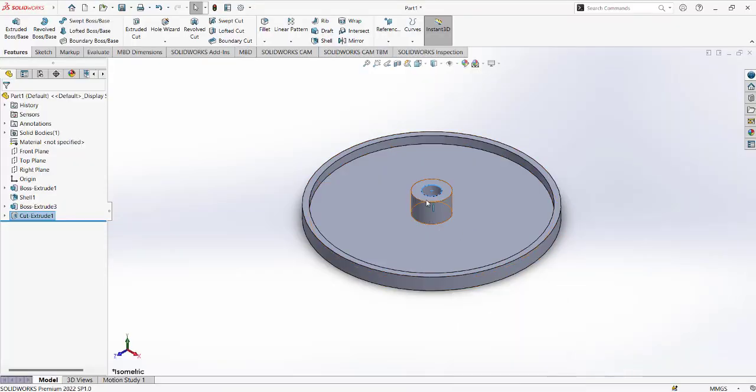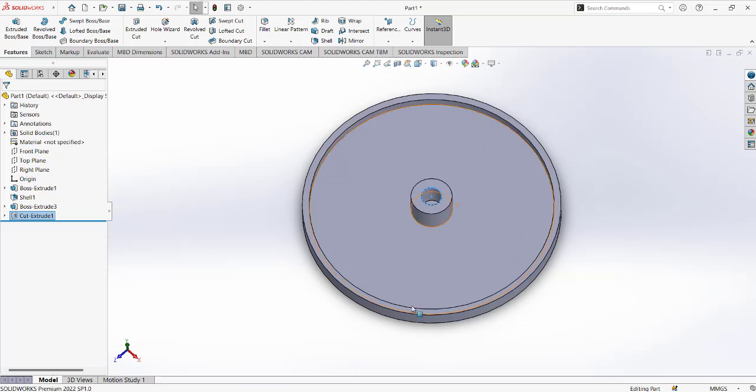So yeah, it's exactly like pointing that, touching this particular face. The next thing is to create the ribs. SolidWorks comes with these advanced features where you can add ribs using the rib feature, instead of creating lines here and then extruding them like these. We can use the rib feature to create the ribs.